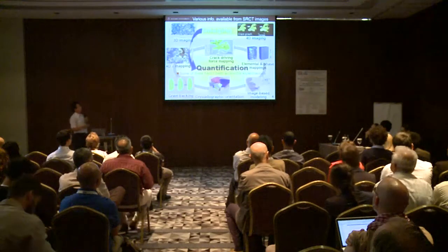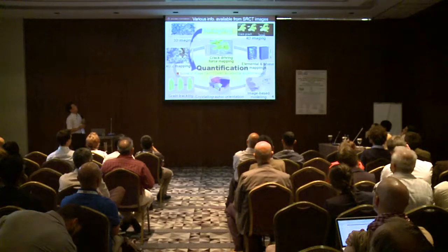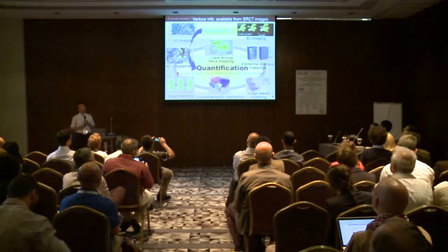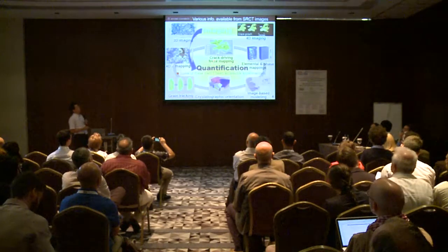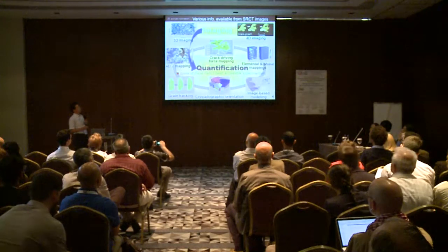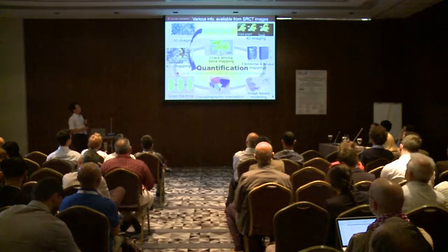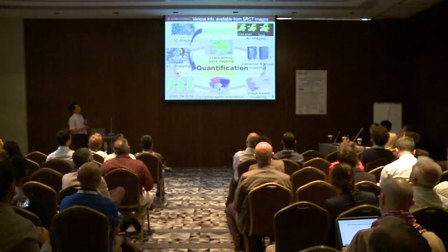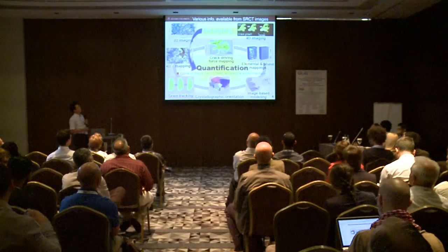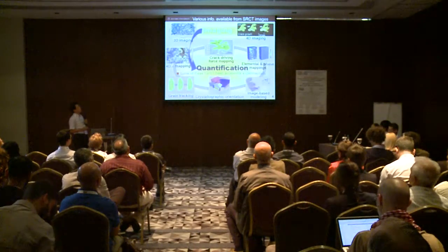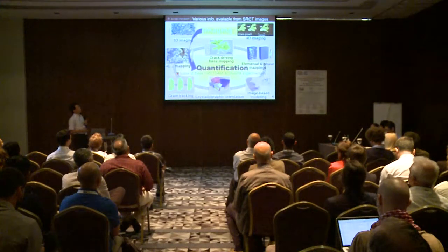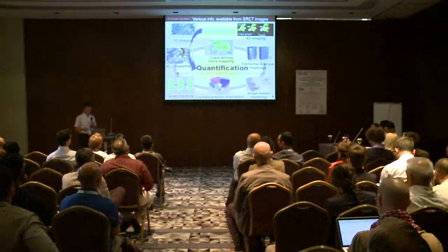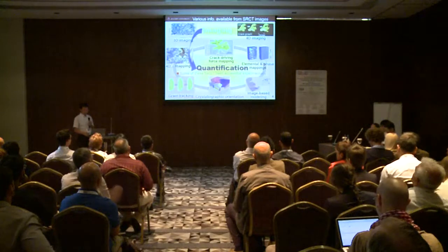So this is the content of the present study. We are going to apply state-of-the-art 3D and 4D imaging techniques to see what is happening inside aluminum alloys. We have also vigorously developed some image-based quantification techniques, such as 4-dimensional plastic strain mapping, crack driving force derivation along the crack front line, elemental and phase mapping techniques, crystallographic evaluation techniques, and so on. We are going to use some of those techniques to see the linkage between hydrogen embrittlement and hydrogen trapping.